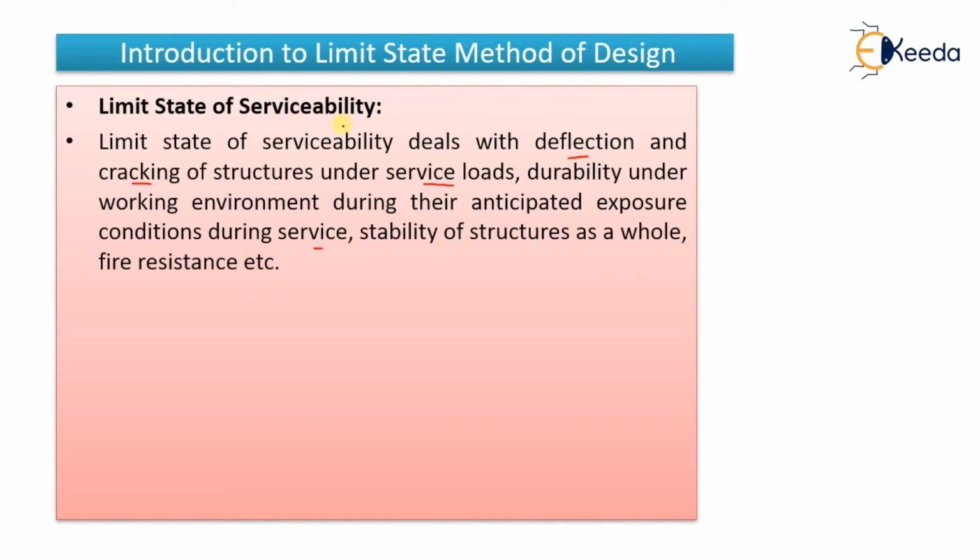For serviceability, we will check deflection and cracking under the service loads, and we will check its durability, whether the structure is durable or not, and for that particular exposure condition it should fulfill the criteria. It should have fire resistance, it should have proper stability, it should fulfill all the requirements. So that is your limit state of serviceability.